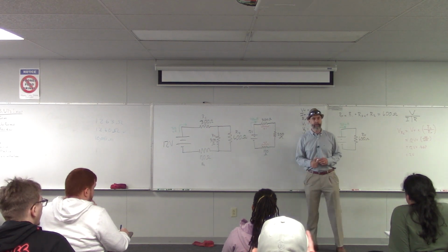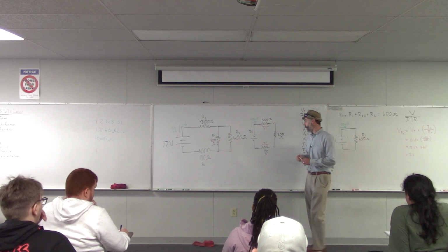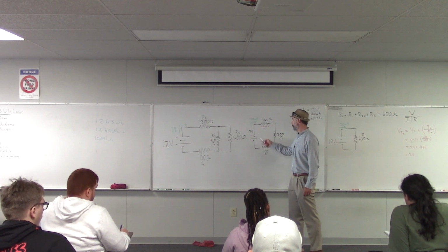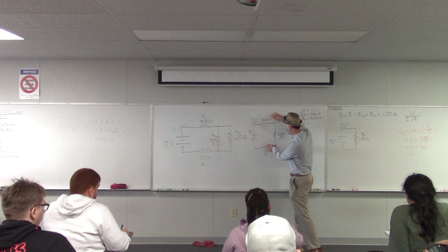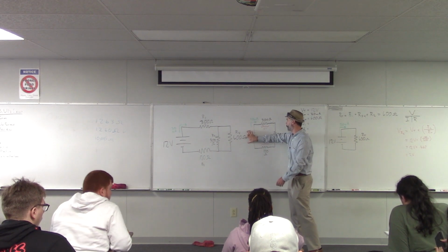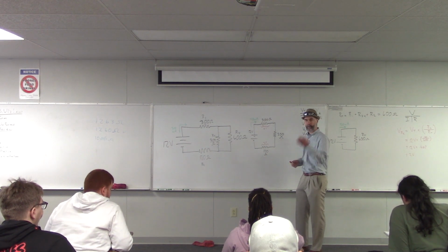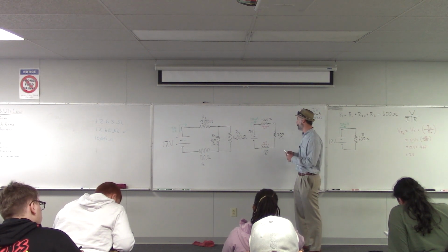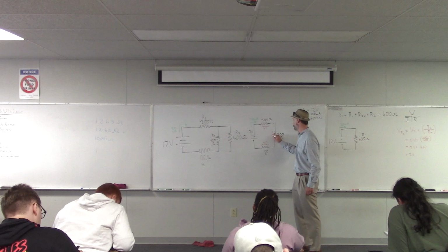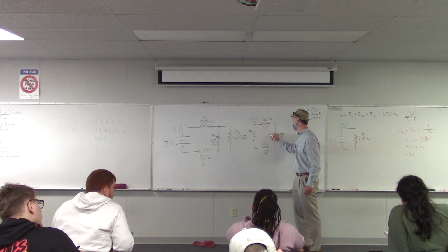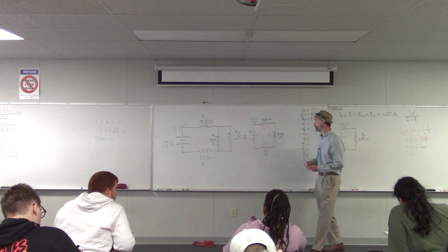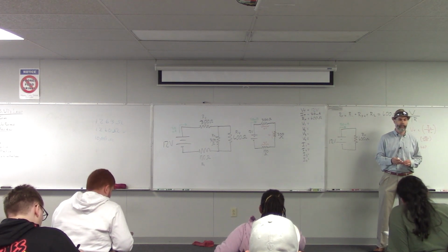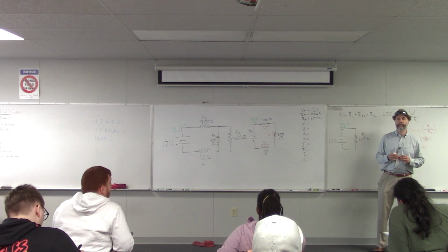And then, what's that? I have 4 left. That's exactly right. Yeah. So all of the voltages around this loop have to add up to 0. In other words, these resistor voltages have to add up to the 12 volts of the power supply. So like you observed, we've got 6 volts there, 2 volts there, that's 8 volts. So the rest of the voltage, or 4 volts, has to be across that resistor. So questions about that? Yeah.